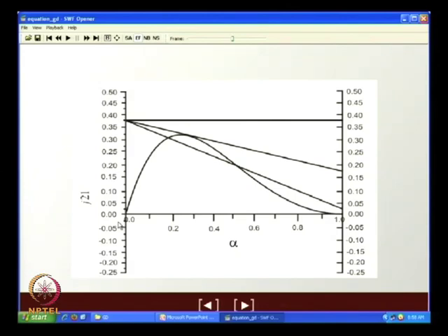So, for countercurrent flow with gas up, liquid down, we all know that it operates within a particular stable operating range, and that range is limited by the flooding condition at one end, the weeping condition at the other. Okay. So, below the flooding point, we find that we can get countercurrent operations under two conditions. One is at low alpha, the other is at high alpha. The point at lower void fraction denotes the bubbly flow situation. The point at higher void fraction denotes the droplet flow or maybe the wispy annulus sort of flow condition.